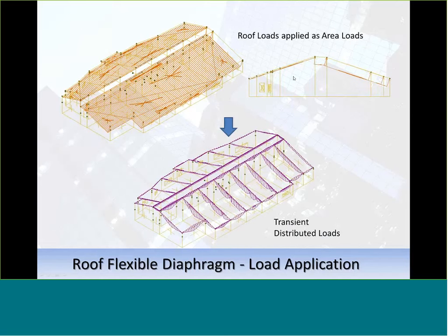And what that does internally is that turns that also into transient distributed loads, and we get to see that transient load distributed on that wall element. So all of these walls have those distributed loads along their perimeters. And this gets broken up into the X and the Z coordinates, or directional loads there. So you're going to see that kind of combination of loads applied into that wall. So you get to see that uplift right there. Very similar to a floor load on a flexible diaphragm, but in a floor we'll just see that one point load.